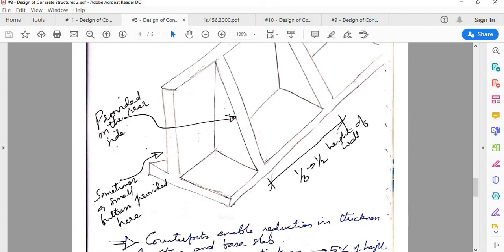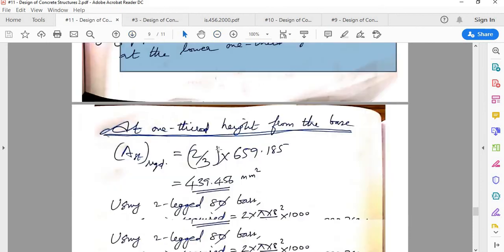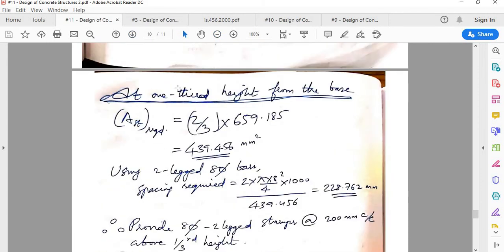Similarly, you need to provide vertical stirrups connecting the heel slab and counterfort, so that it will prevent detachment of this interface, because remember, the heel slab is subjected to downward pressure, right? So that downward pressure we had calculated earlier. So let us design that vertical stirrup now.